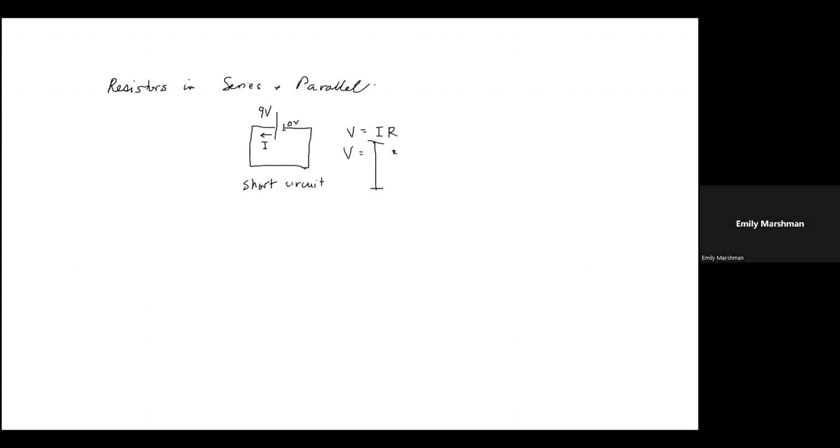And so this is a bad thing to have in your home, right? You would think, oh, I don't want that much resistance. Well, actually you do want some, because if you don't have any resistance or very little resistance, you're going to get a lot of current flowing, and that's not good for your battery. And it's also not good for your house, right? If you've got a short circuit in your home and this wire is getting really hot, there's a potential for a fire. So that's another thing you will explore in the lab today.